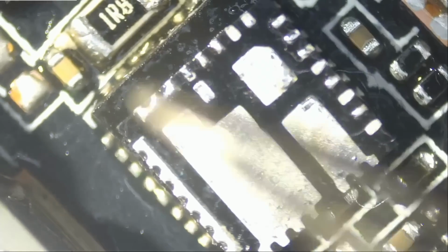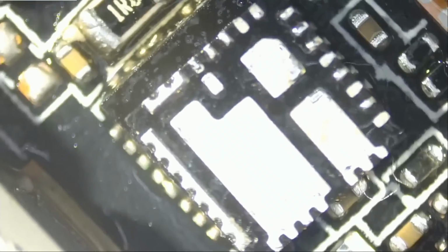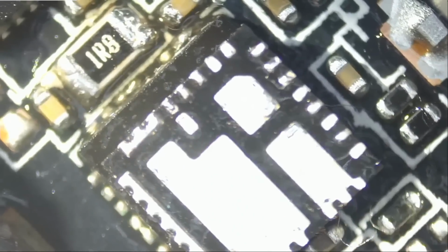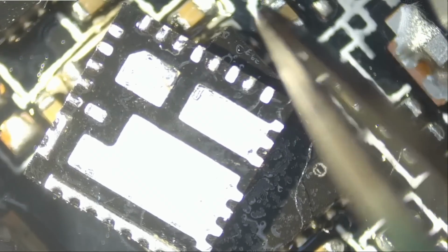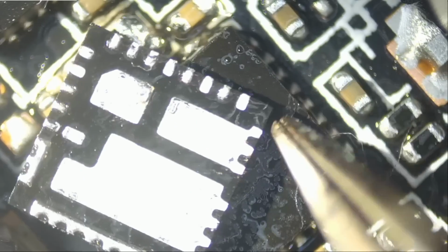This end will be here and the bottom end should be on top when the chip is flipped. You can tell that pin number 1, 2, 3, and 4 are the same pad. They should bridge. It's okay for them to bridge. And then pin number 1, 2, and 3, they bridge. And all the pins on the top, they are connecting as one. So it's okay for those to bridge. And you can tell on the bottom we do not have any bridges. We should not have any bridges on the bottom.